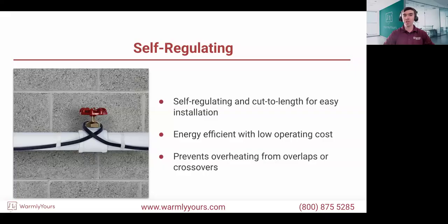That's where the advantage of the self-regulating cable becomes really prominent. Let's say we're using 300, 400 feet of cable. You will have a section that really needs to work overtime and heat at the highest wattage. It will do its job because it can sense that. But maybe on the other end,